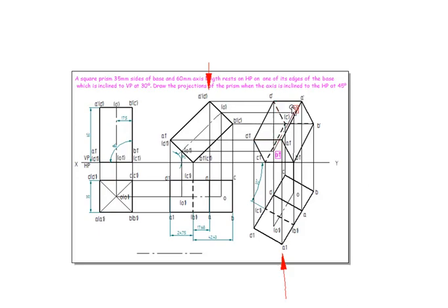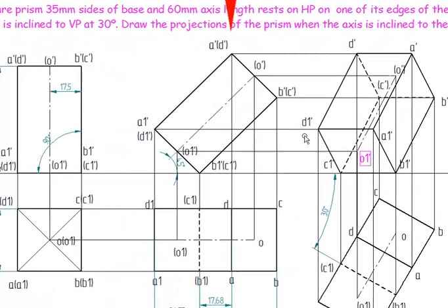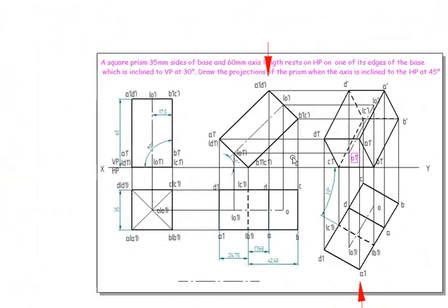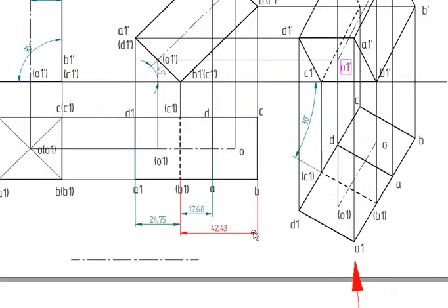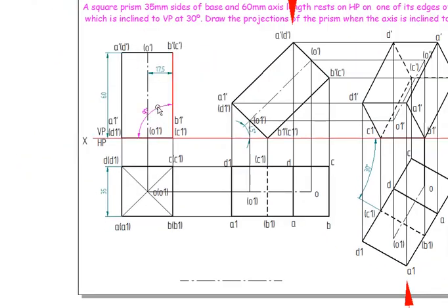A1, B1, B, A is thick line. A1, D1, D is thick line. D1, C1, B1, A1 comes under the bottom face which is visible. So these dimensions you need not retain. This is just for your reference. Whatever the solid has given, we need to maintain. This 90 degrees is for your reference. This 70.5 is for your reference. This is a square. So make sure that you are going to add prefix.